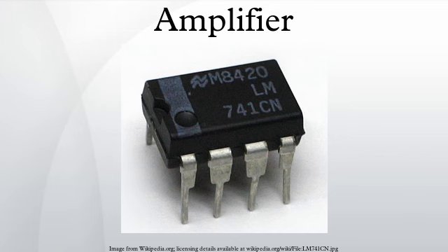The bias point of the carrier and peak tubes is different, and is established such that the peak tube is cut off when modulation is absent, whereas both tubes contribute twice the rated carrier power during 100% modulation. As both tubes operate in Class C, a significant improvement in efficiency is thereby achieved in the final stage. In addition, as the tetrode carrier and peak tubes require very little drive power, a significant improvement in efficiency within the driver stage is achieved as well.